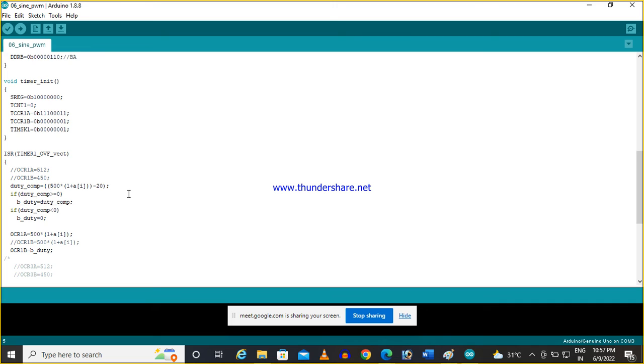Say my dead time, I have calculated the dead time as 20, okay. So now you see here I am defining a variable called complementary duty, and here it is 10 bit. So arbitrarily I took 500, you can take up to 511 or 512. So always it is better to take slightly lesser. Your teacher, Ayon Banerjee, I think he is there, he taught us in that way. So always you need not put the full resolution. Okay, so that's why I gave here 500. And you remember the formula I told, resolution by 2 into sine theta plus resolution by 2. So this is basically that formula, and minus 20.